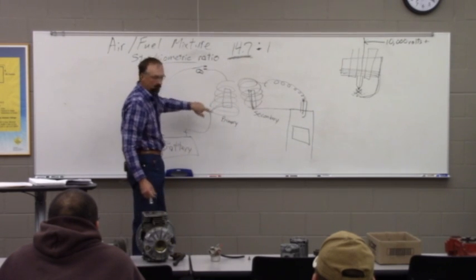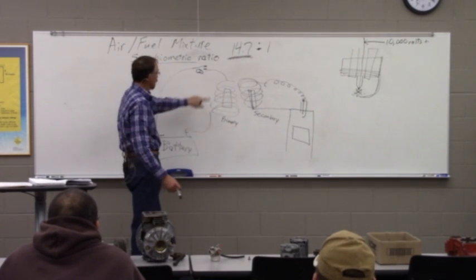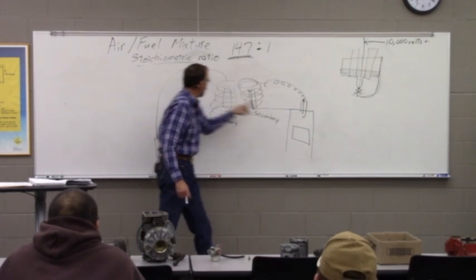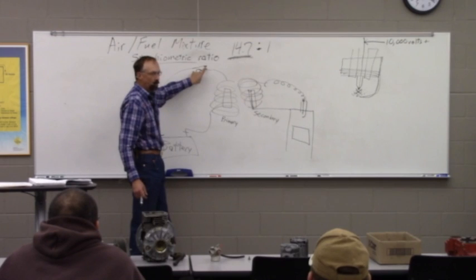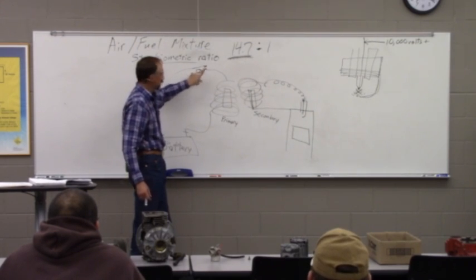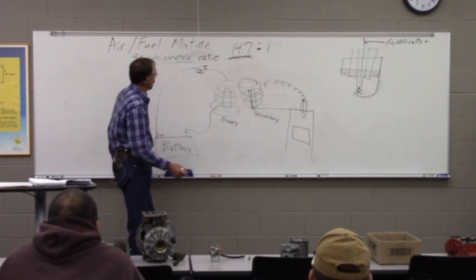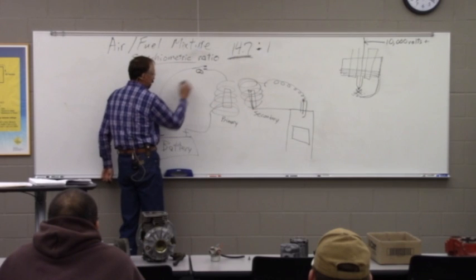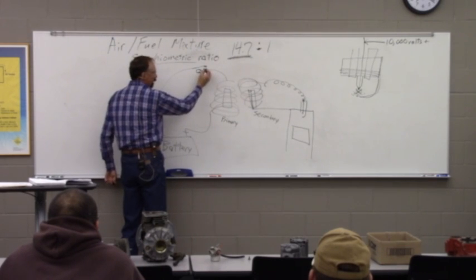So if you're looking at the correct direction of rotation, you'll have this spark happen in your cylinder right when these come open. That's when the spark is created, not when they're closed. Now we would also have a tendency for this power right as these come open.